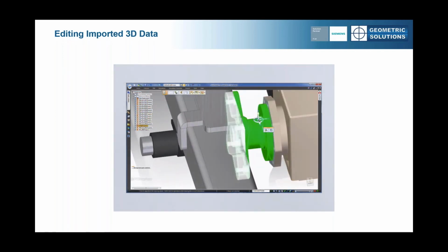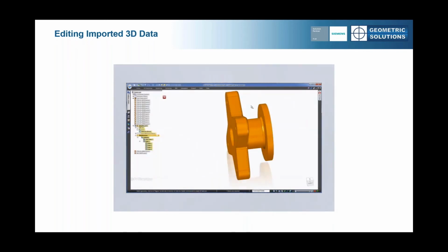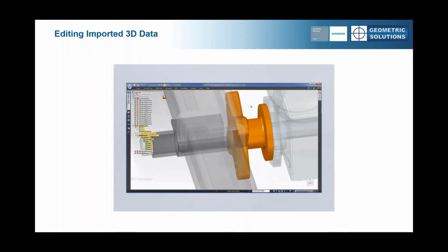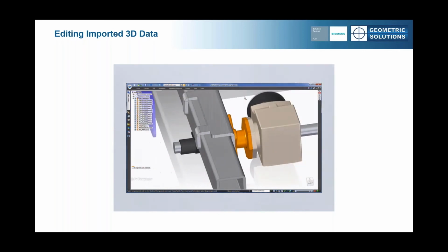After getting the motor in position, we can see we have a mounting issue. The two flanges don't quite match. Not a problem though. Synchronous technology in Solid Edge allows us to easily grab geometry sizing from one part and use it on another. Sorted. We obviously need to make more room for fastening hardware, so let's make some more quick edits here.